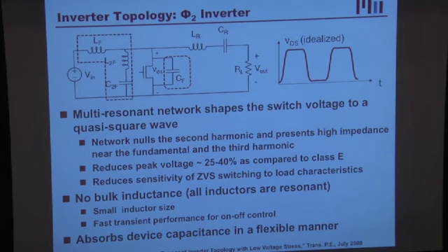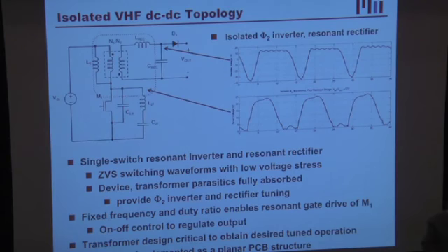How do I turn that into a power converter where I said maybe I want to take DC in and generate isolated DC out? Well, what I would do is I would take this and I would implement the same kind of resonant network, but I would bury the resonance in as part of a transformer. Okay, so this resonant network that I showed you on the last page is still in here. It's just buried in the front part of this transformer.